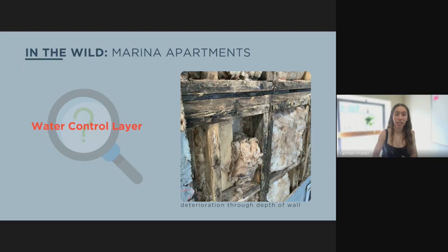The fluid applied in this case, it's semi-permeable, but the fluid applied wouldn't have been under as much hydrostatic pressure for as prolonged of a time because, again, that moisture, that bulk water would have been running down the drainage plane. There would have been airspace with some ventilation in there for it to dry out. If they had used something like a more robust impermeable sheet product, I'm talking about something like a Permabarrier. Now, when you install something like that, you also have to consider condensation risk and exterior insulation and all of that. But if we took condensation off the table and we were just talking about it from a bulk water management perspective, if they had used an impermeable, more robust sheet product, it likely would have been okay.